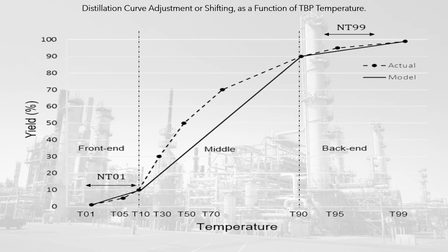This will have the desired effect that we can alter the amounts of evaporation in the downstream mixture to better control and optimize the mixing quantity and quality specifications to meet market demands. However, when we handle TO1 and/or T99 for any distillate component flow, these values, interconverted to DO1 and D99 if necessary, must be sent as set points to an appropriate advanced process control strategy in the operation of the respective unit. These strategies are available for analyzers that can be linked to pump heat exchangers and temperature controls to achieve the desired increase and/or decrease in initial and final cutoff point temperatures.